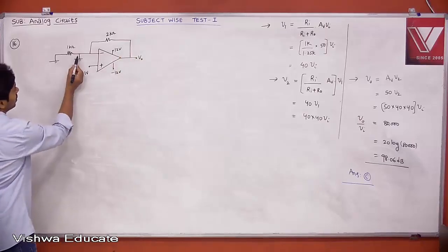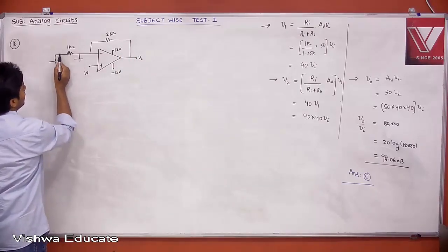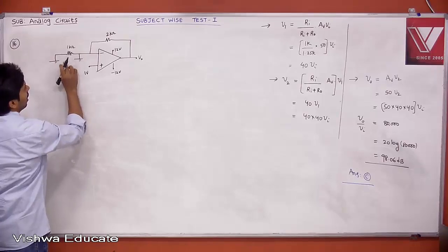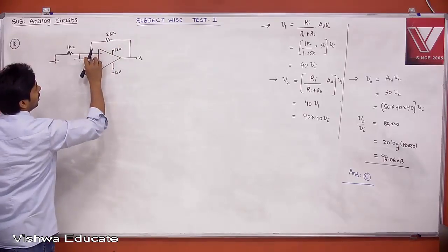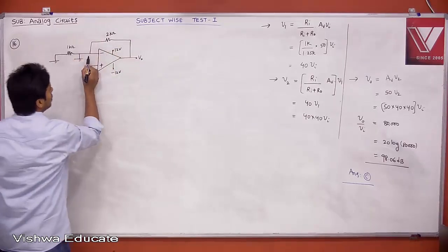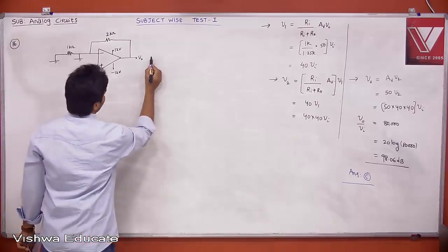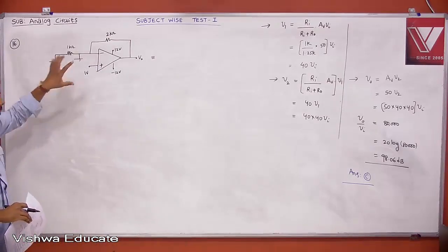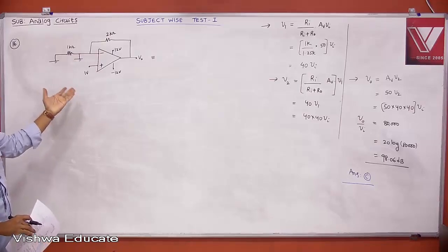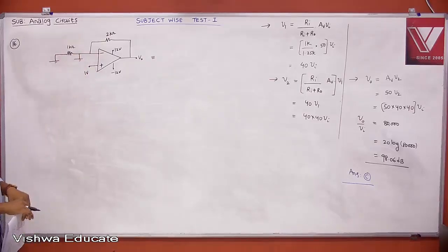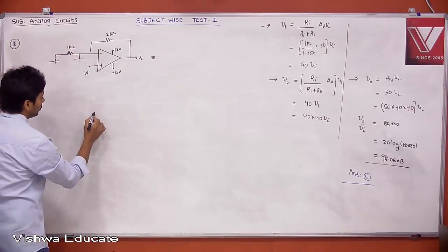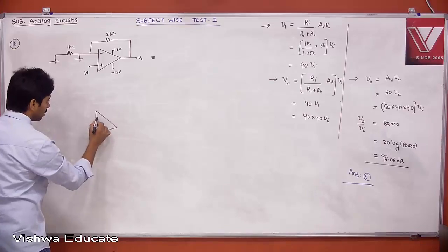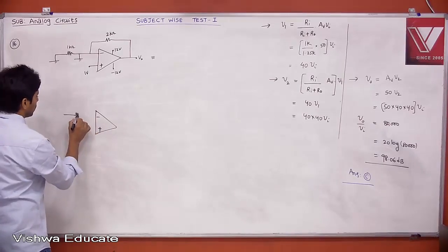But because of this ground, what does it mean? It doesn't have any significance. And this is also not having any significance. There is no feedback. If this is ground, can I write this as equivalent like this? Remember, if you overlook the circuit and think non-inverting amplifier, then 1 plus R2 by R1, you will get it. Remember, if this is the circuit, minus plus,